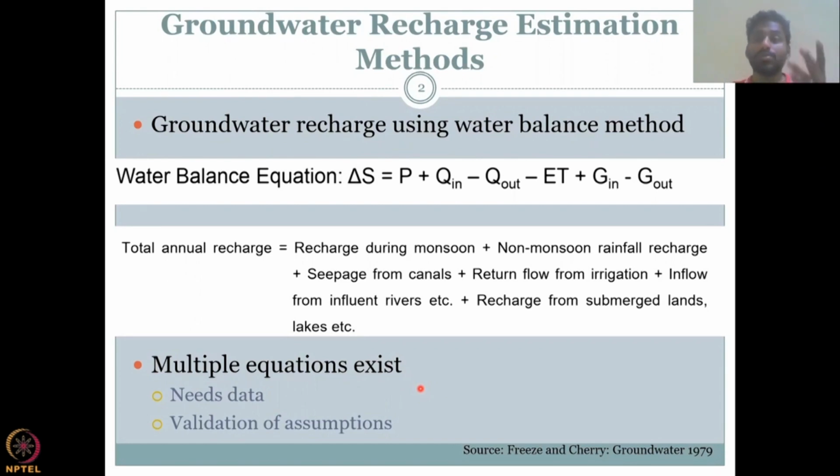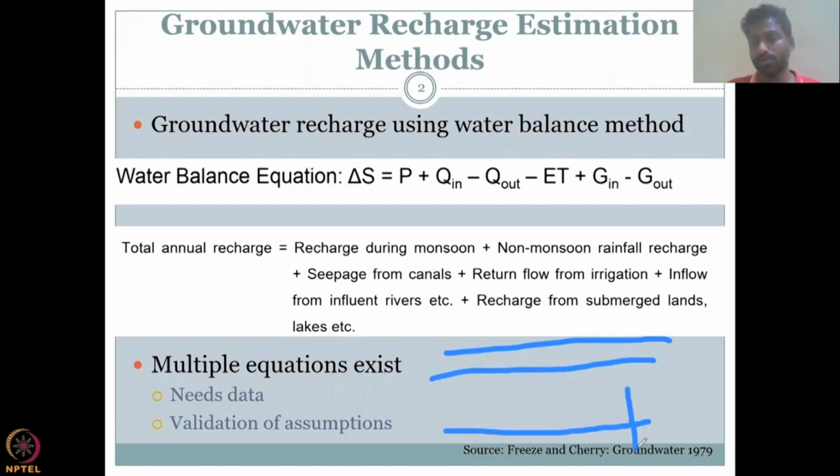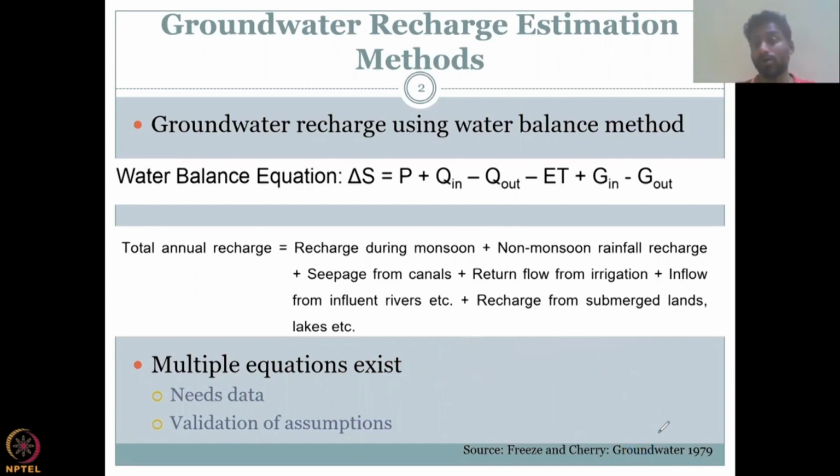Okay, what if the pipe is leaking? Then there's recharge to groundwater because it goes inside the ground. So you have to think about how, for example, this is the ground and this is your big water pipe connection. There should be some water leakage, and that can also contribute to groundwater recharge. Sewage systems contribute to groundwater recharge. It's bad quality, but quantity-wise, yes, it increases. So countries like Nepal have a lot of these old water supply schemes, and there are always leakages.